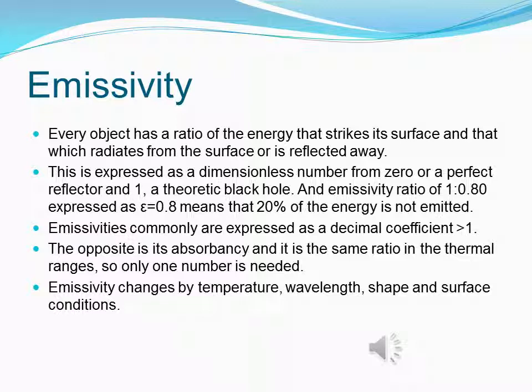The desalination device that I showed in an earlier presentation was made of 316L stainless steel, which has a low emissivity. So we had put a spiral scratching on the device to make a pattern out of it, make it look nice, a swirl design on it. That increased the emissivity that it gave off.